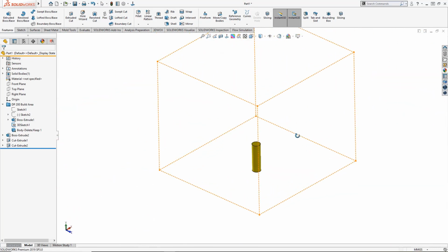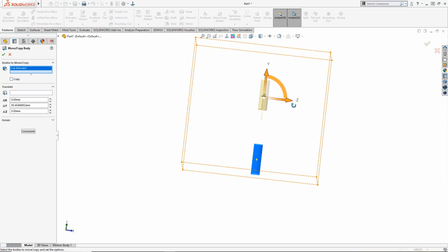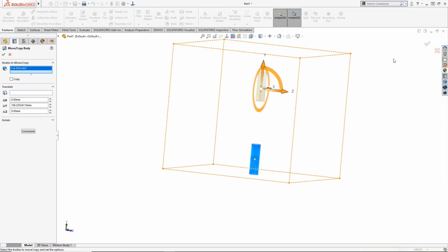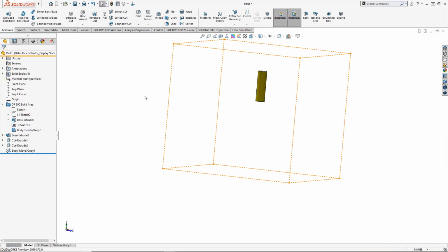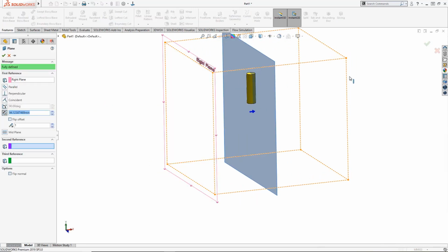And really all I need to shape and size my feature. Now I'm going to plan to build this thing upside down. You might wonder why that is, but I'll show you a presentation I did a little while ago that describes this. The goal here is I want to build it upside down because I want to build it with as little or no support structure as possible. And there's methods that you can do that just by the way that you design things.